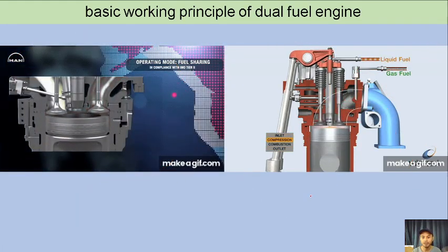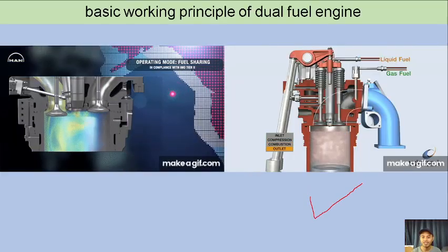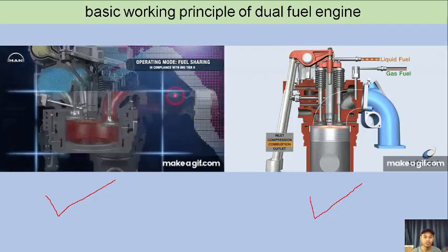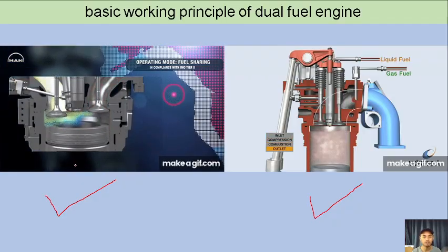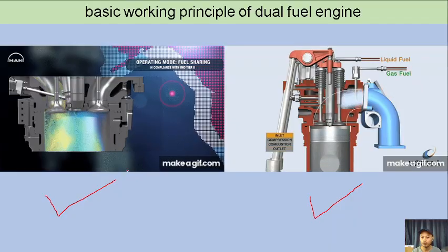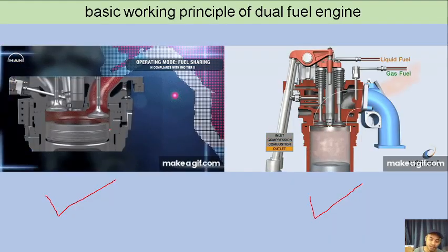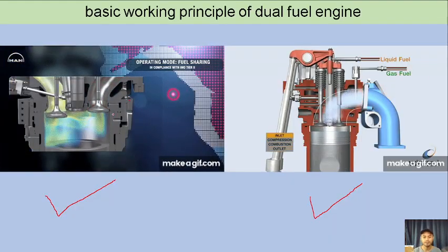So the difference in both, okay, let's erase. So the difference here: gas fuel is injected during the intake stroke, but on this type of engine, gas fuel is injected during the compression stroke. So both use dual fuel, both gas fuel and liquid fuel. So that's the basic working principle of a dual fuel engine.